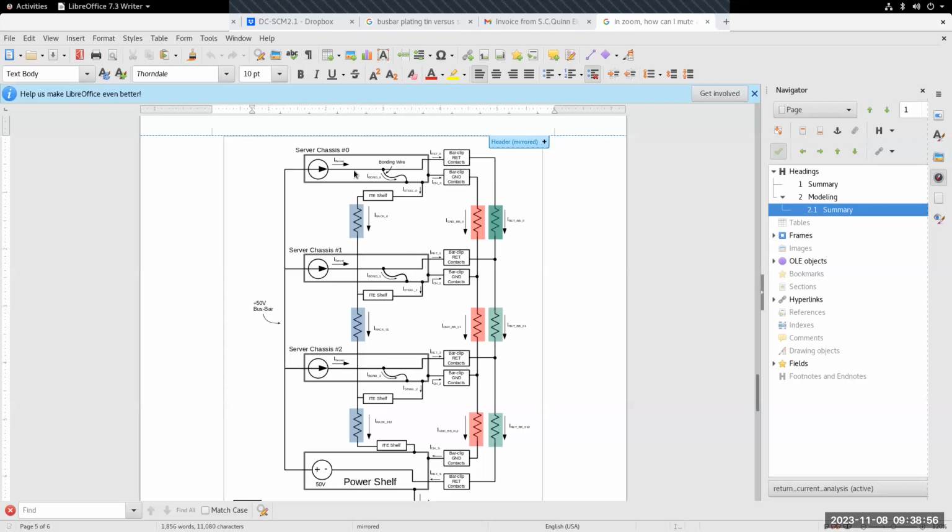In the first experiment we did, the load was shut off on the top server, and on this server I had a 20 amp load, and of that 20 amp load, 15 amps went into the return bus bar. 25% of the current took an alternate path, and it appeared to go into the rack steel, and then up to the top server, which was mated.